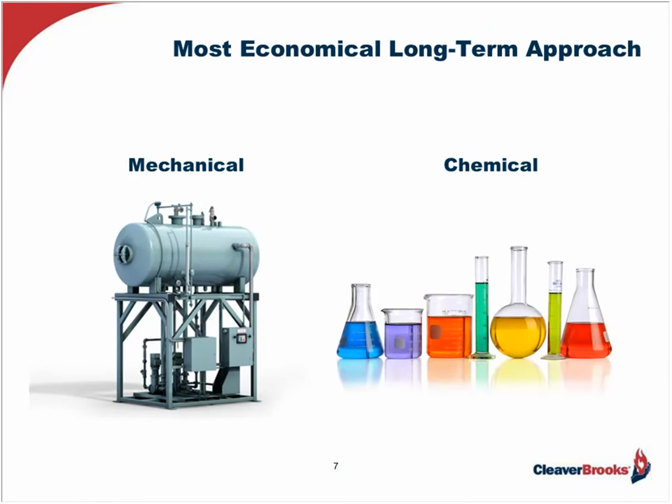So as we stated a few months ago when going into detail about a sound water treatment program, deaeration, though a key factor in attaining a highly efficient and long-lasting boiler system, can't do it alone. We still need chemicals to finish the job, and the amount of chemicals employed will depend on whether other mechanical devices are in the system, such as water softeners, dealkalizers, maybe an RO, those kinds of things. But suffice to say, at least to some degree, chemicals need to be part of the overall solution.